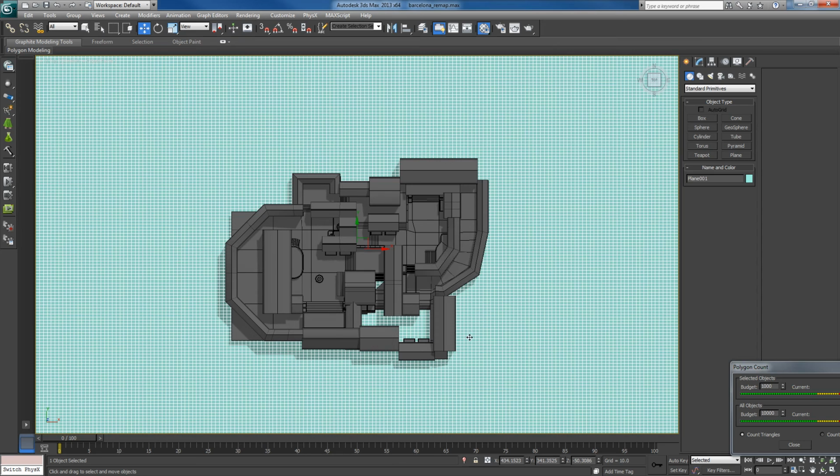It's ideally suited for hard body objects, like, say, for example, an oil drum. To get the kind of resolution out of an oil drum that we would need to make it look like an oil drum, 8 segments is not going to do it. So we'll have to pump that up to 24 before it starts to look good, and then from 24 to 32 it starts to look smoother, and of course 64 would be considered high detail. So that's the kind of thing that you can build with this.